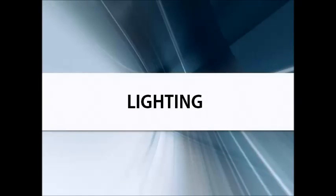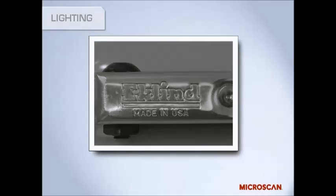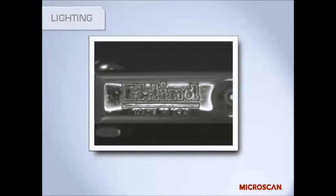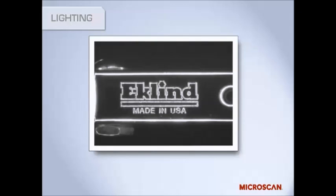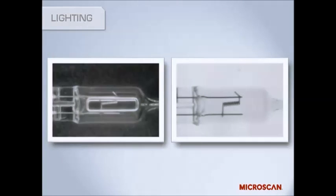Proper lighting is critical to the success of an application. The type and position of a light should be carefully selected to maximize contrast of the features you plan to inspect and minimize contrast of everything else. This is like an electrical engineer setting up a system to give a high signal-to-noise ratio. You're trying to make the pieces you need to see, or need to measure, very clear, and you want all the other items in the image as invisible as possible. To give you an idea of how you might do this, let's look at some examples.